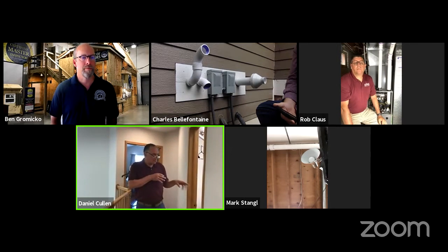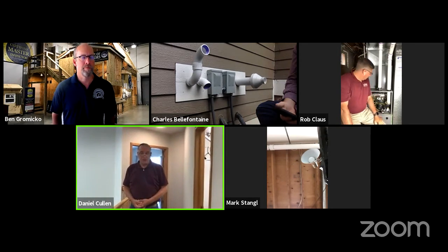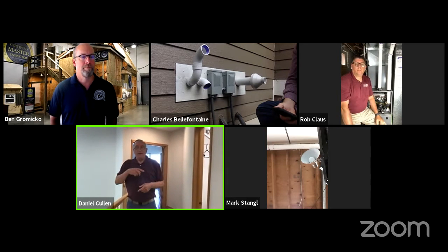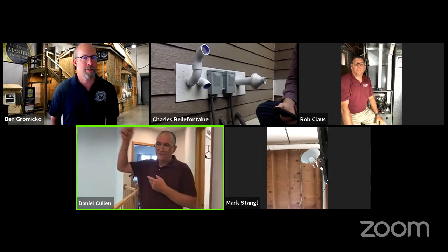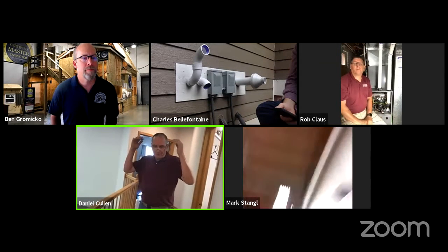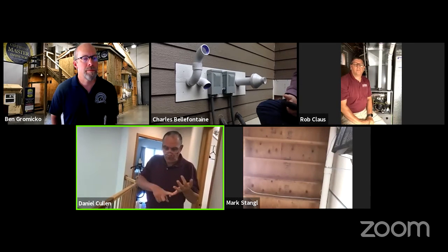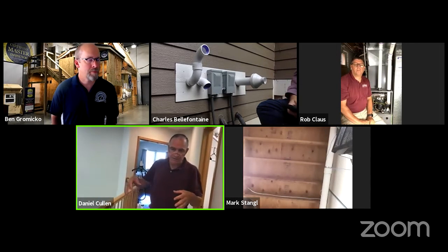These are all things that I like to look at. In addition to the more technical things about how the unit is operating, I like to look at the furnace in the context of the whole building shell, the windows, the attic. And I didn't finish that ABC concept of weatherization. So after the attic, then basement. We don't have a basement here, but in a typical house with a basement, after you've done your weatherization in the attic, your insulating, air sealing, and ventilation, you want to focus your energies on the basement, because the rim joist areas are very, very leaky.